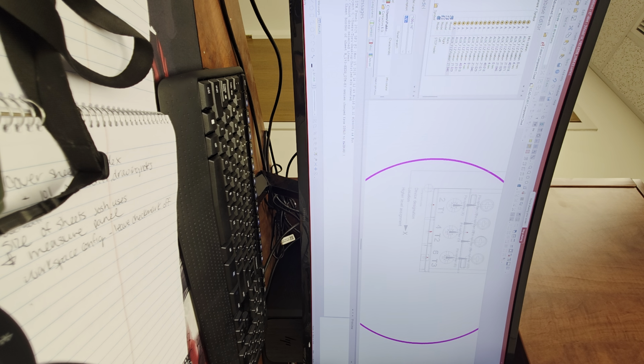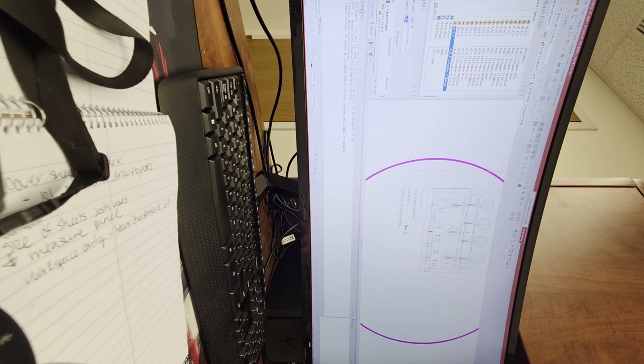If you click in the header between the component/symbol and info column, that little separator window, there you go, we can make that a little wider. Now normally if I were to design such parts, because I'm trying to make my life easier, I would usually, instead of just calling everything aux-f, because really it's too broad of a comment, pick one to say, okay, this is for my starter, this is for my jumper, this is for my whatever those items are, as I'm looking at them to be my end items. So you can right click on these aux-f as an example.